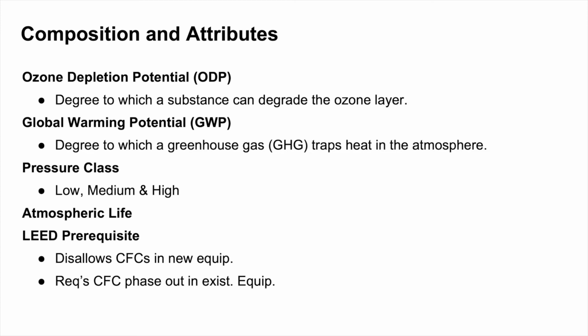That's the normalized refrigerant that we use for comparison's sake for all these. In addition to those two very important attributes, pressure classification is something us as consulting engineers and designers need to focus on. That has impact to equipment size, size of the actual refrigeration machinery based on the pressure it's going to be operating under. Atmospheric life is important, right? This is the duration that this refrigerant is going to stay captured in the atmosphere if it ever were to leak out of its vessel. And certain refrigerants will linger around longer and have more of a detrimental impact to the atmosphere.